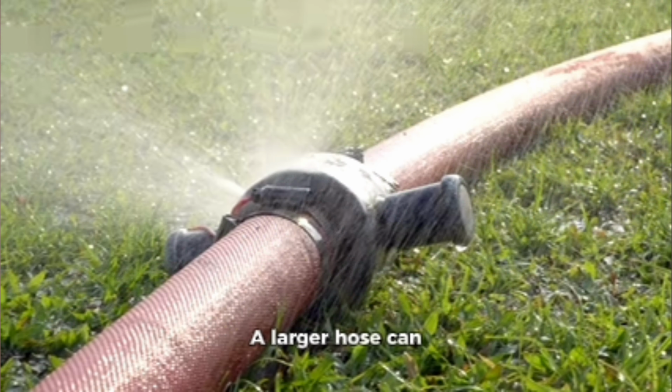Getting the right cable size is crucial. Too small, and you risk overheating and potential fire hazards. Too big, and you're wasting money. So how do you find the sweet spot? First, you need to determine the current that each circuit will carry. Remember that total power load we calculated earlier? We'll use that along with the voltage, typically 220 volts for single-phase or 380 volts for three-phase systems, and a bit of math to get the current. Don't worry, it's not rocket science.